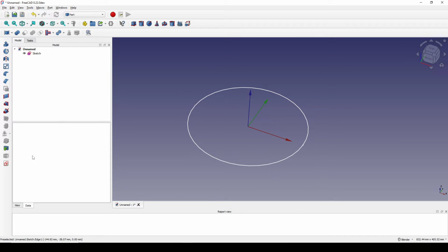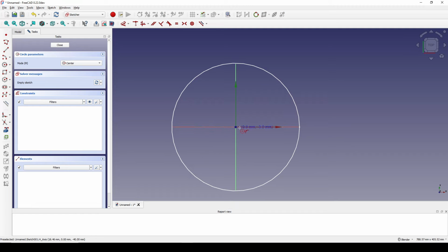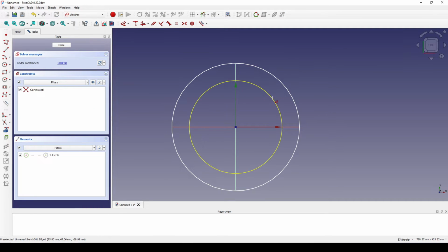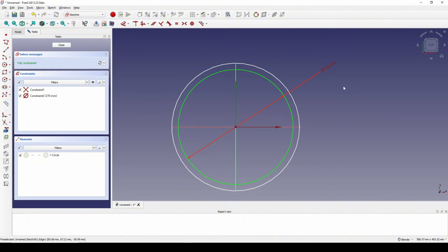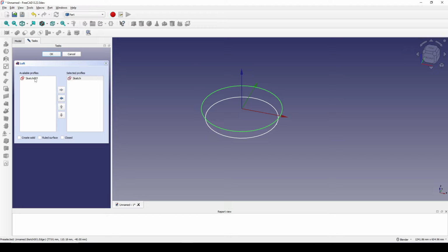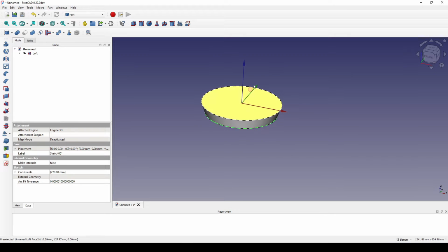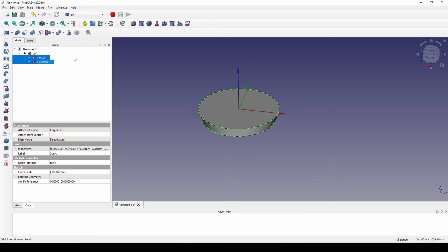Next, I create another sketch in the top, but I offset it. Negative 40. And I create another circle. And I set the diameter to 70. I close. Now I will loft between these two and create solid. Click OK. I drop this one down and select these two and hide it. Hit spacebar to hide it.